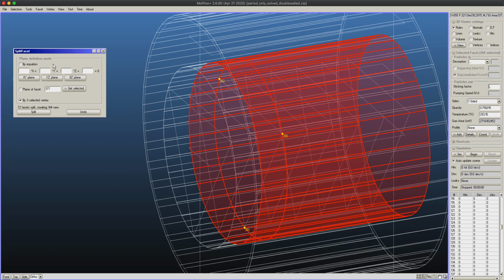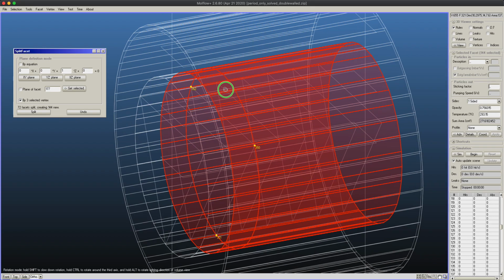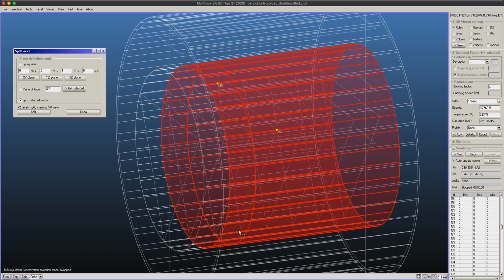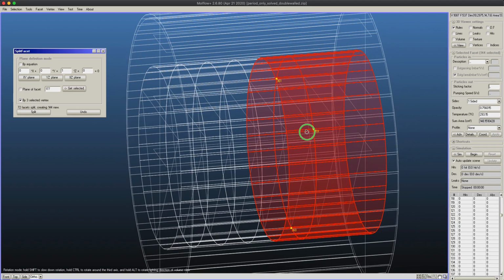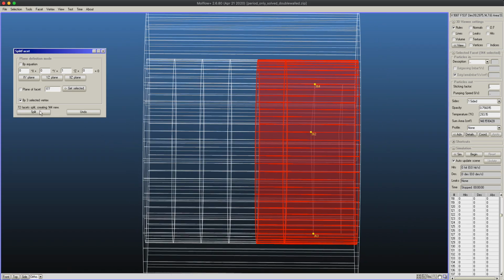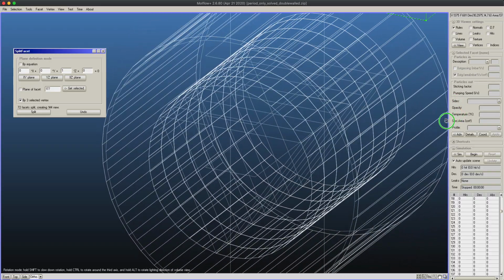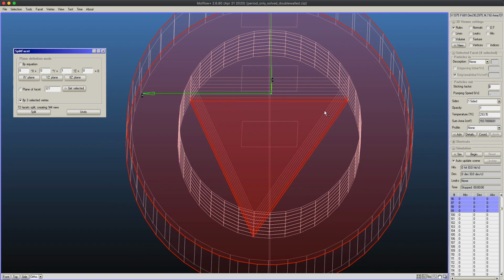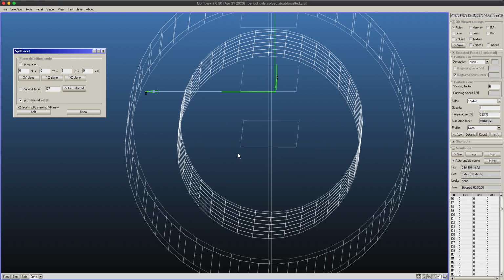What you could also do is manually write the equation of the plane, and the offset from the xy plane would always decrease by 1 centimeter, but I don't like that because here I take advantage of the orientation of my geometry, and you could have an arbitrary geometry. So it will take a little bit of time, but I will very quickly do all the splittings. Since these triangles are in the middle, if I go for a side view, I could make a very quick selection, and then I could finish my splitting. Right now, we don't need these splitting planes anymore, so I will delete them. Okay, facet, delete, everything is left.